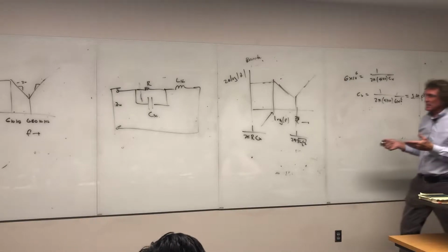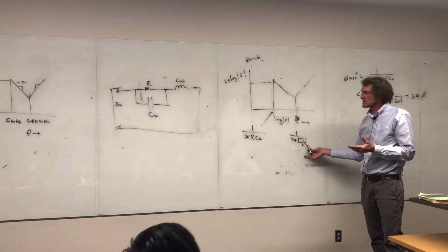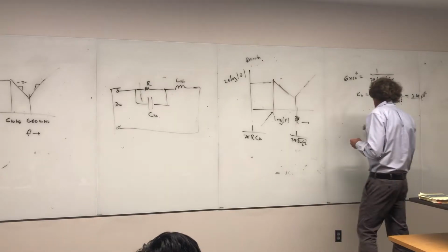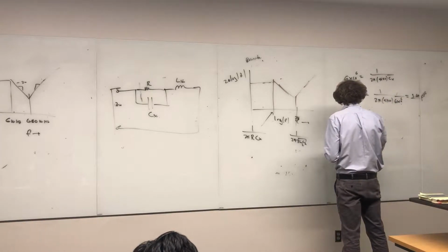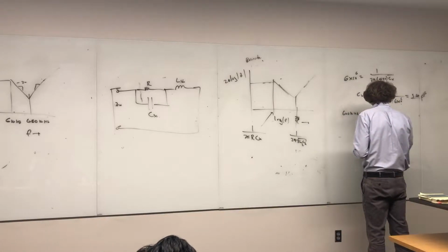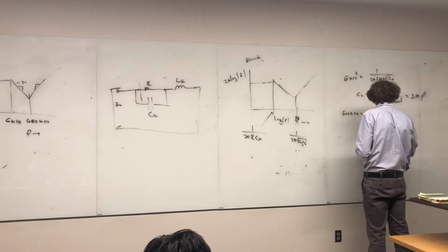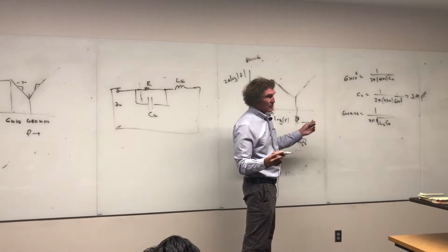Now, to get the inductance, it's pretty straightforward because there's your next frequency, and that was 600 megahertz. So 600 megahertz is equal to 1 over 2 pi times the square root of L C, L lead and CX. You can rearrange them yourself, but you'll know what I'm going to be doing.